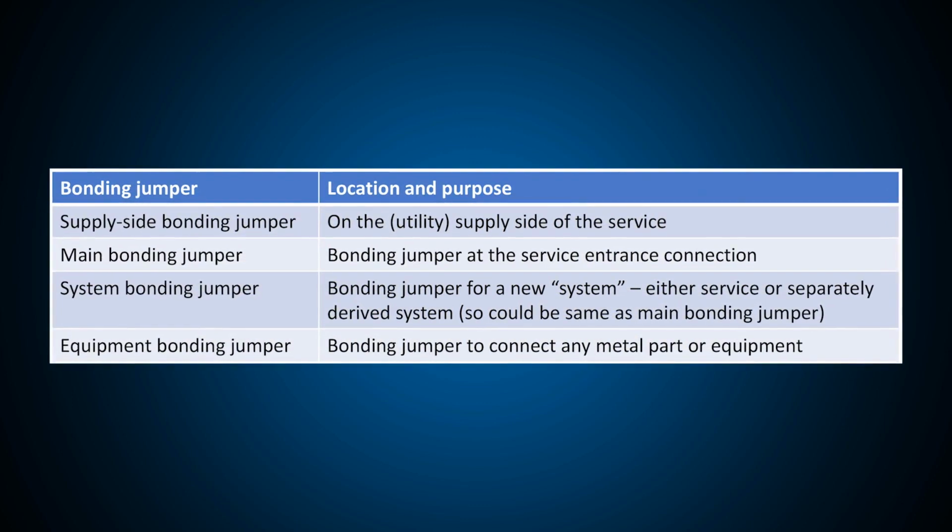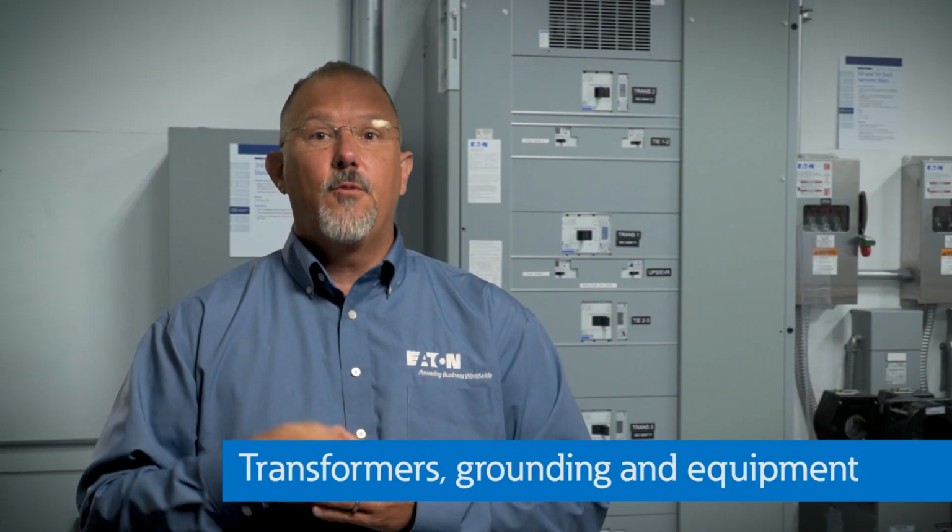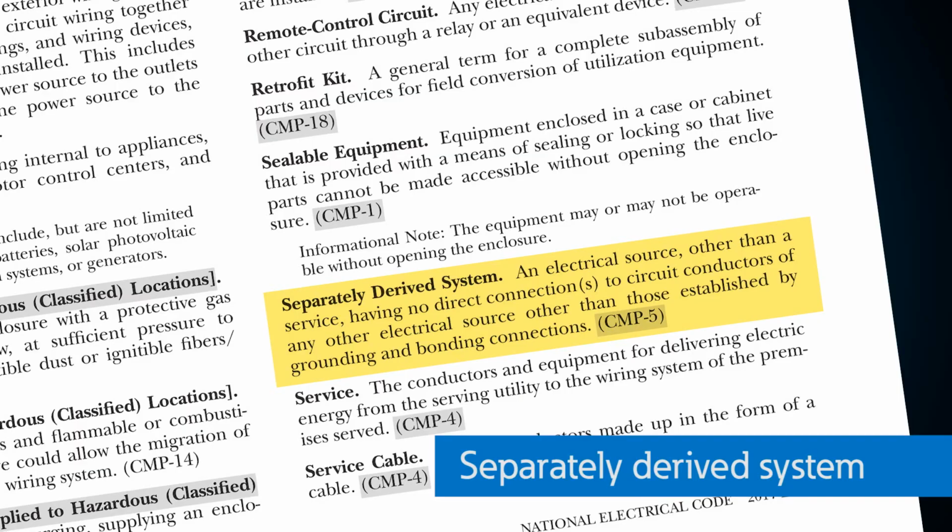Now we're going to move over to transformers for grounding and bonding inside of transformers. When we move into a transformer, we're talking more like in a separately derived system. This is your electrical source, other than a service, having no direct connections to circuit conductors of any other electrical source other than those established by grounding and bonding connections. That's your separately derived source.